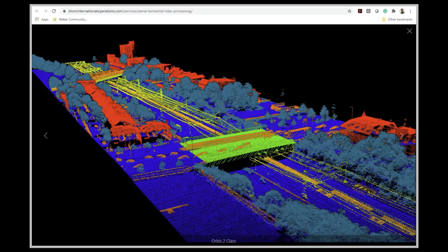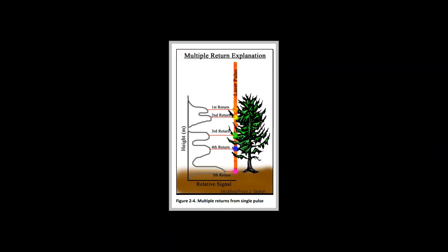up to the airplane. What that really means is that as they shoot a laser pulse to the ground, so this ultraviolet light to the ground, they are getting multiple returns per second for each one of those pulses returning back to the receiver and giving them indication of both the ground and the features that are above the ground and how dense those are. Creates this massive 3D point cloud of information.